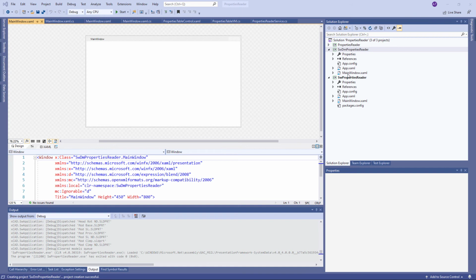streams, which means that you do not even need to open file in SolidWorks or even have SolidWorks installed to access this data. And the performance of this operation will be sometimes hundreds times faster than the equivalent of SolidWorks API. This library is free, but you need to have a SolidWorks subscription in order to receive the license key which is required by this library. Please follow the link in the description of this video for more information about Document Manager API.